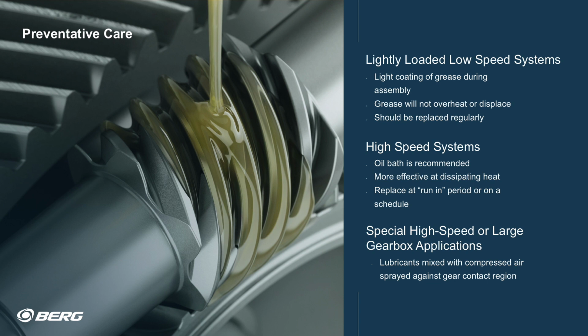For high-speed or highly loaded systems, an oil bath may be the preferred solution. This system will have higher thermal capacity because the oil will be in contact with the gearbox housing and can conduct heat away more easily. However, churning of the gears through the oil will take additional power and generate more heat. The oil bath may also require a change following the run-in period or through a regular schedule.